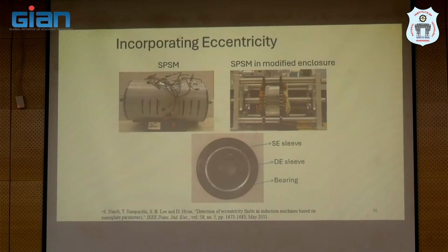permanent magnet based motors. If you have invested in a permanent magnet based motor, then I have shared the second research article in which you would have seen the enclosure is modified in such a way that you don't have to remove the bushings. There will be screws that you can push in or pull out, and that will adjust the level of shift offset that will be applied onto the shaft or to the bearing.